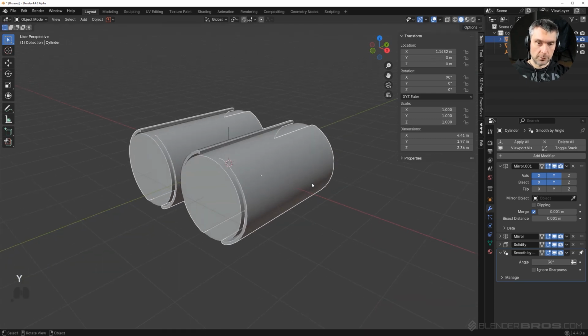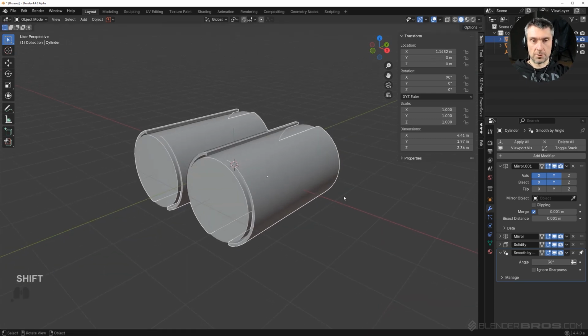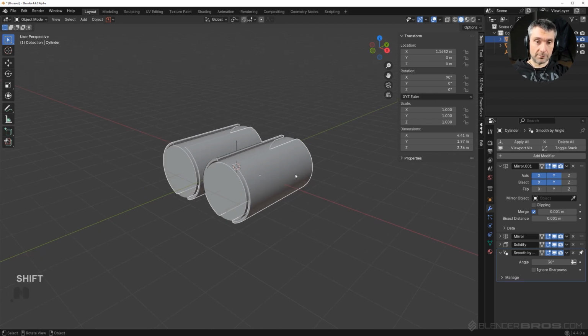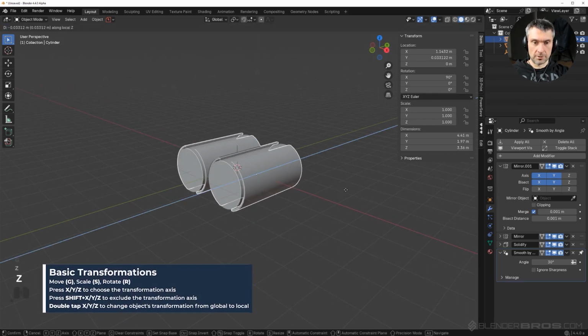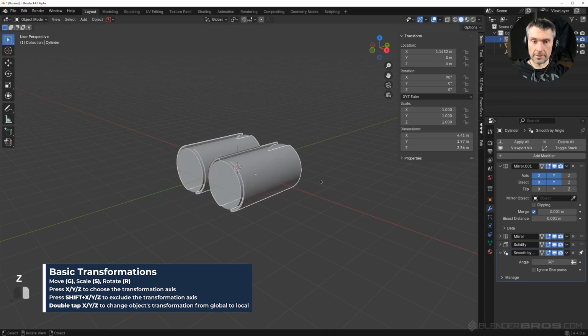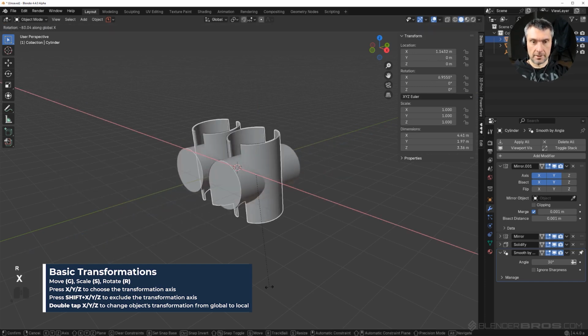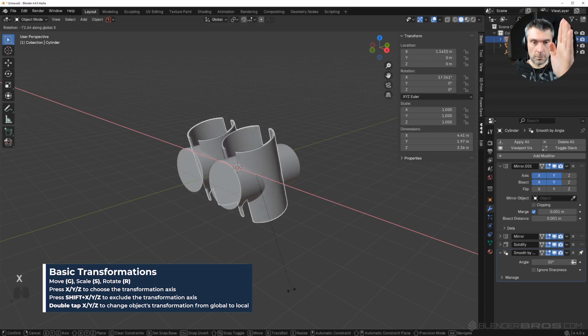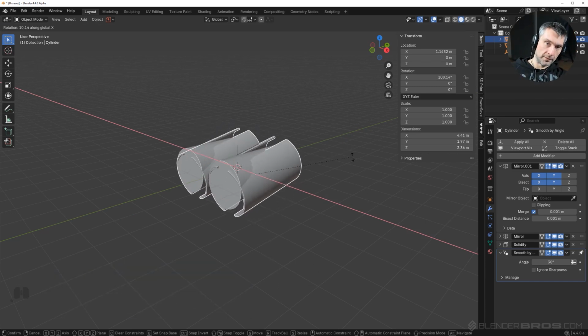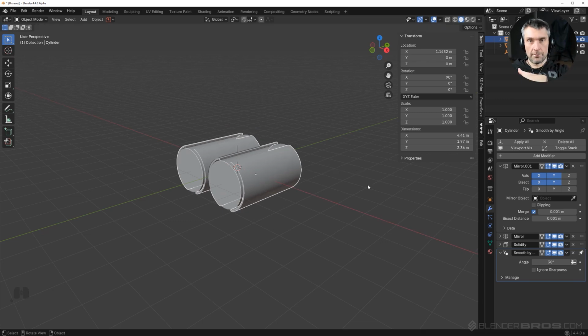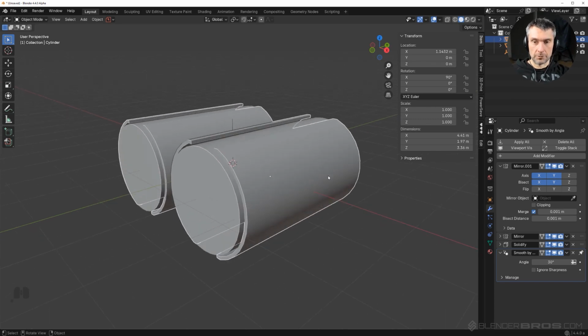So this is a bit confusing, but if you're going to apply rotation, things gonna reset. So z-axis for this object is actually here, GZZ, right? That's a local orientation because we rotated it, remember? The cylinder was vertical, like this. Z-axis was here. We rotated it, so it went 90 degrees to the left, you see what I mean? And the y followed, so now y is vertical. So you need to kind of remember about this when you're modeling. Otherwise, you're going to be confused, okay?